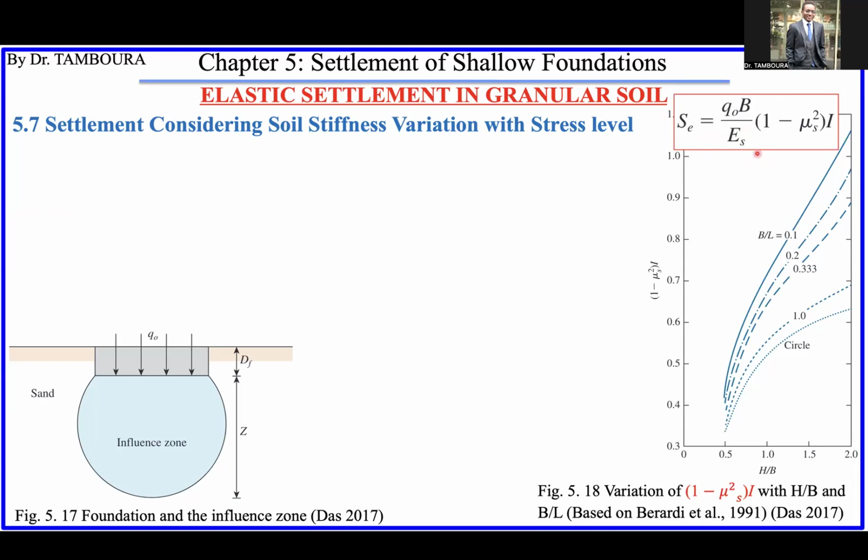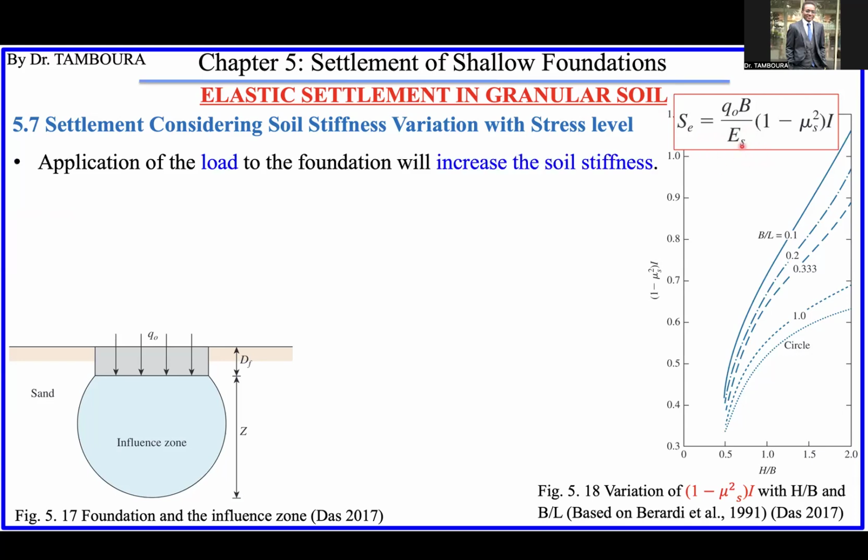Let me keep this equation here, the general equation. So application of the load to the foundation will increase the soil stiffness. So this is what I was saying. When you apply the load, if the soil was loose, the stress will increase the stiffness of the soil.